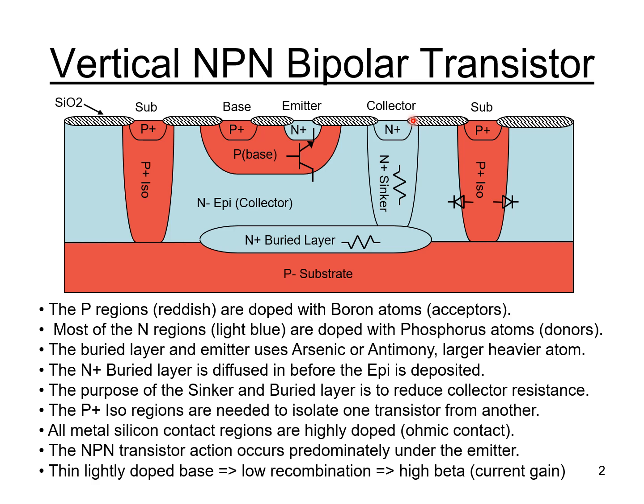The buried layer also serves another subtle purpose. It will kill the vertical PNP. It's a substrate PNP formed between the P base region, the N collector region, and the P substrate region. And by putting that buried layer underneath the P base region, that gives you a high dope base region for that vertical substrate PNP, and that pretty much kills its beta.